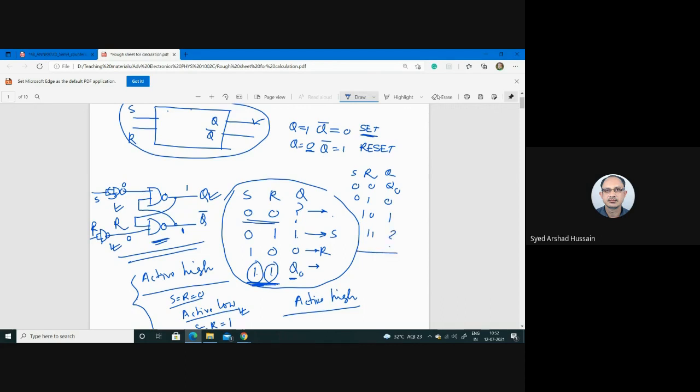So this is a circuit which will rest in low state and will become active whenever you change any of your inputs from 0 to 1. For example, if you want to reset, you change this R to high. If you want to set, you change your S to high. Then you will have either reset or set. Both high is unwanted. So this is how you do it.